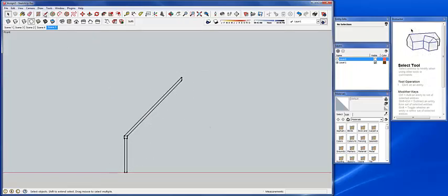Now in order to do that again, we're going to build a scaffold for that. From edge to edge, we know that that's 24 feet. Hit space, and now we can see that... And just like in AutoCAD, selecting left to right, anything inside the box is selected; selecting right to left, that dashed line indicates anything touching that is going to be selected.